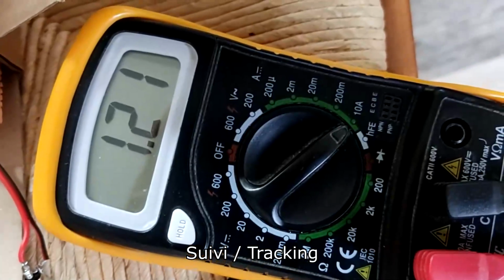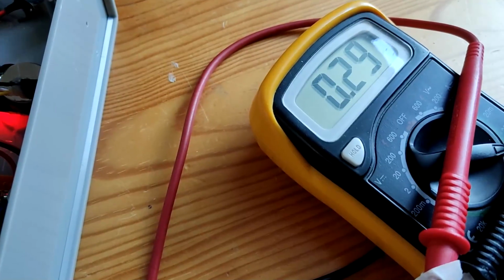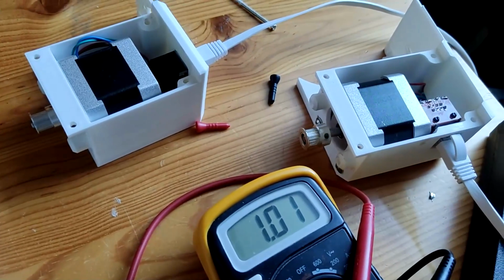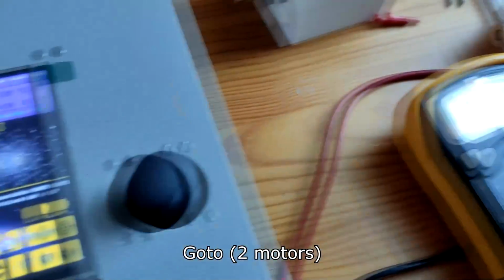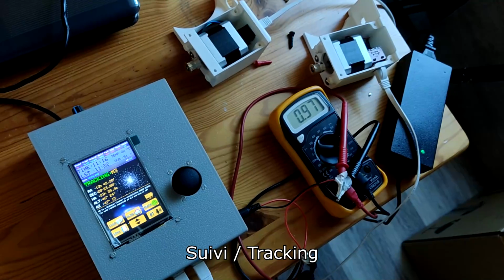After that I tried to lower the drivers' voltage to lower heat and consumption. I had to drill the PCB to access the drivers' screw and restart my test. So at idle this is the same. When GOTO with 2 motors it's about 1 ampere. When the drivers were set at default it was 1.3 amperes. When tracking it is 1 ampere, where we were at 1.2.